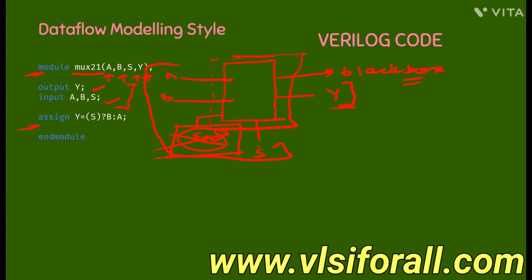So first, we begin with the assign statement, which is how the data will flow inside this entity of ours. For that, we have Y as the output, which will get the value B if S is true, that means if S is 1, and it will get a value of A if S is 0. So the conditional assign statement, to be specific, tells us whether we get the input B or A depending upon the value of S, which could be true, being S equal to 1, and which could be false, being S equal to 0, hence depicting B and A as the outputs for the value Y.